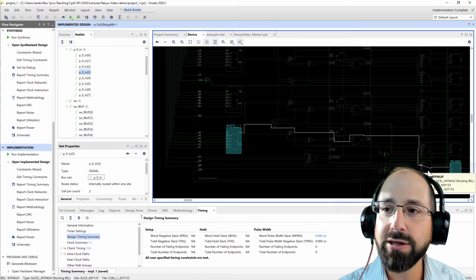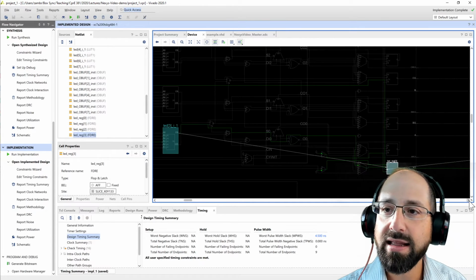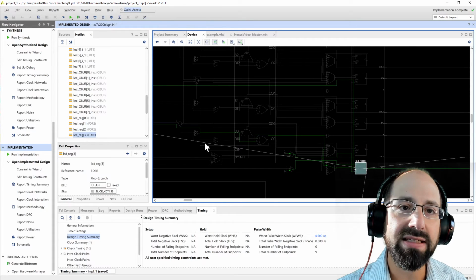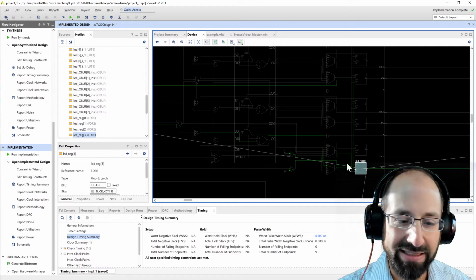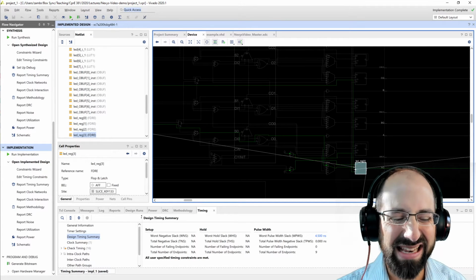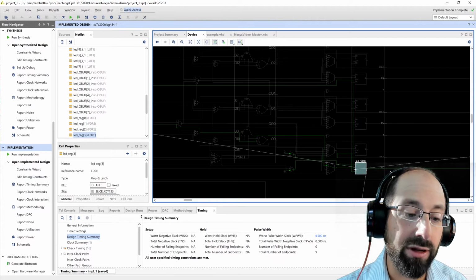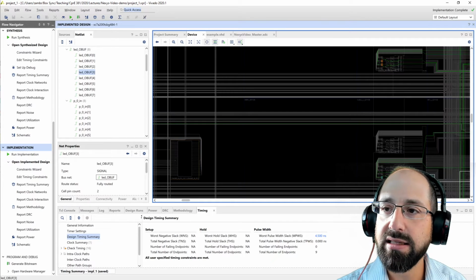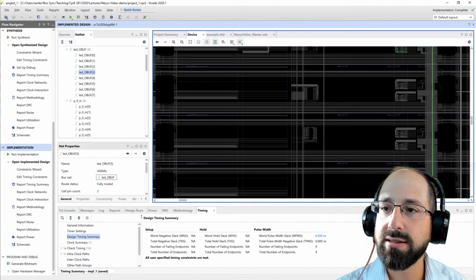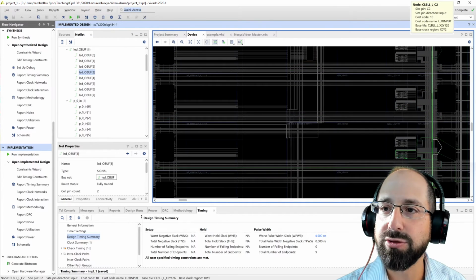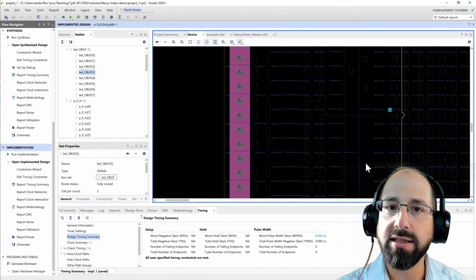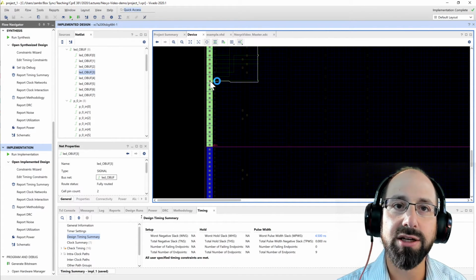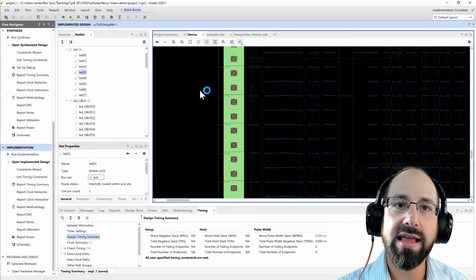Other muxes to kind of locally route stuff, and then finally a little flip flop at the end that is taking the clock, taking the output of our lookup table. And again, these wires aren't meant to be accurate in a three-dimensional space. There's not these diagonal wires going everywhere. Xilinx, I think, intentionally obfuscates a lot of what's happening from a routing perspective. And then the output of that needs to go eventually to an LED, and it's taking a somewhat circuitous path to eventually get to one of the output LEDs, which we can find somewhere in this design is actually going to correspond to that one there. So we can click on that one, and so that's what's getting routed in the design.